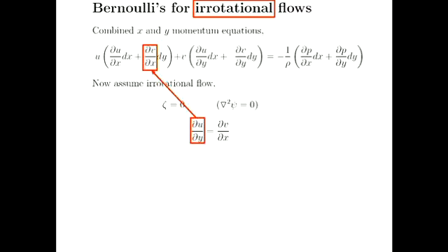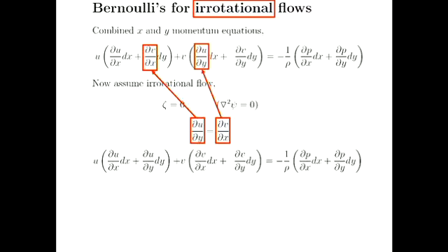And then you've got this pleasing substitution that you can make, so that the dv/dx term in that bracketed term multiplied by u just becomes du/dy, and likewise the du/dy term in the bracketed term multiplied by v just becomes dv/dx, all right? And then we end up with this expression at the bottom here, and now we've got this very pleasing outcome where all those bracketed terms reduce to just a total change in either u, v, or p.